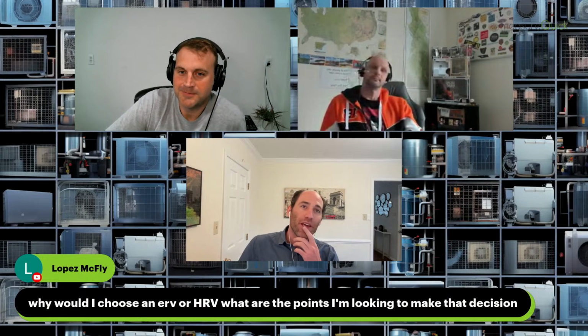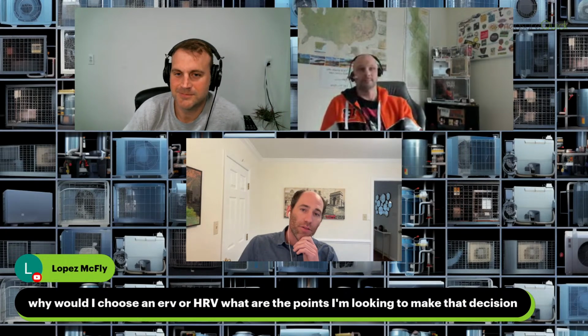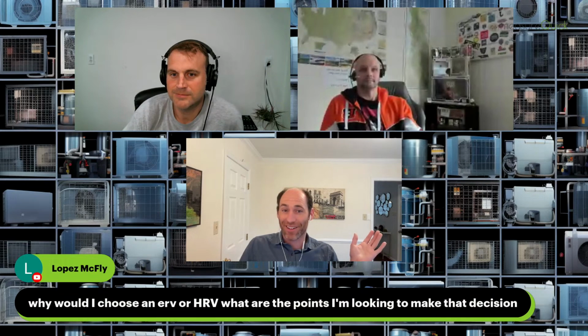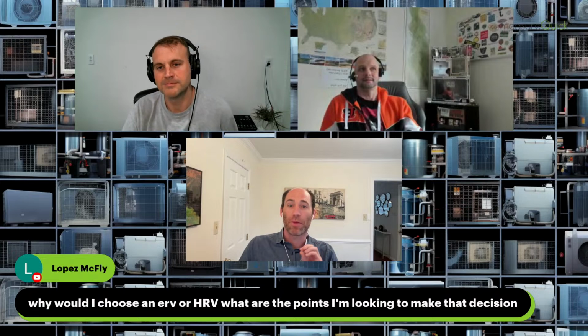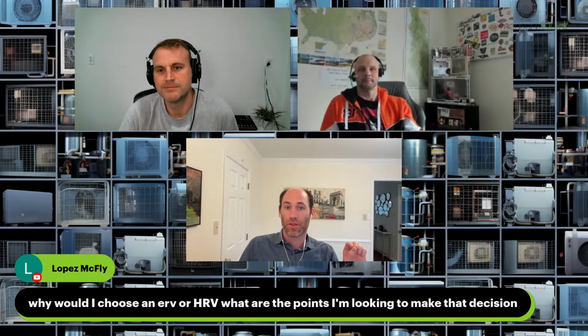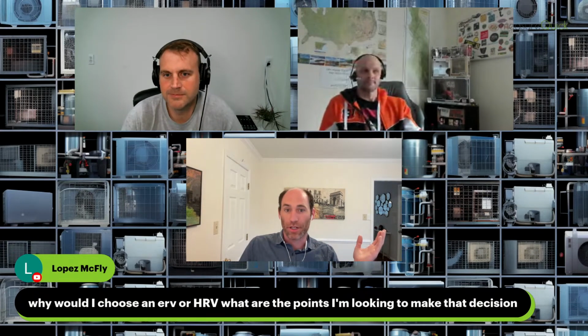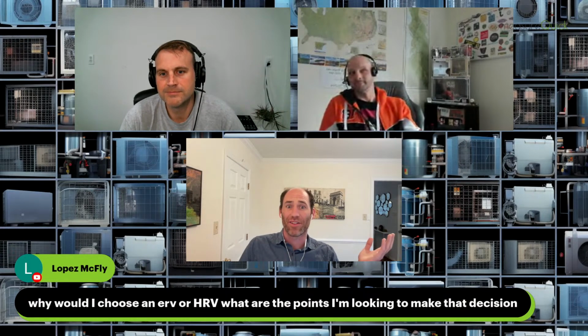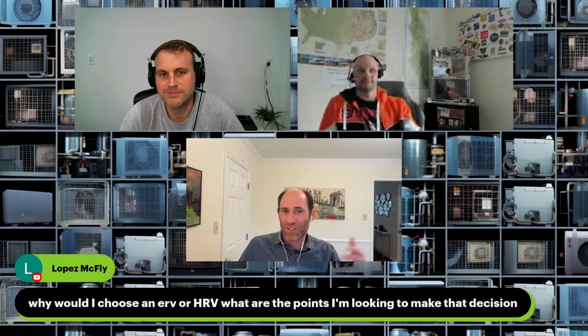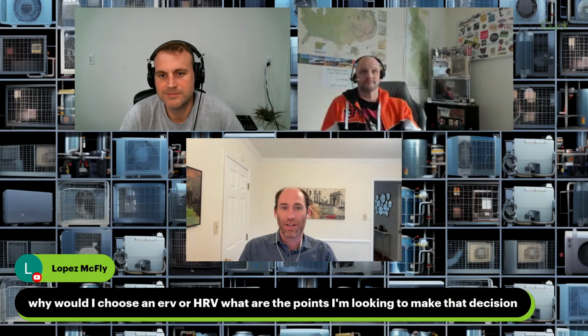So there are some cases where you would want an HRV over an ERV. I've never designed in a climate that does, but I think it's more the climates that have a dry summer, so they can get hot. Let's say like Phoenix, maybe, where it's over 100 degrees outside, but it's dry. So you don't really need to transfer that much moisture. You just need to transfer the heat really efficiently, and that's where an HRV can actually be more efficient at